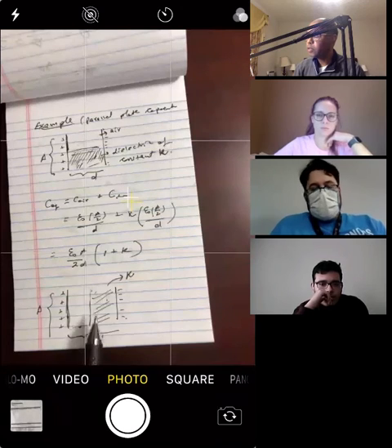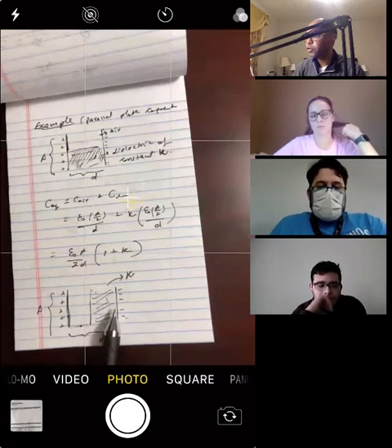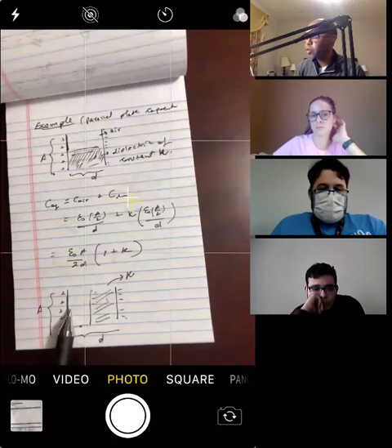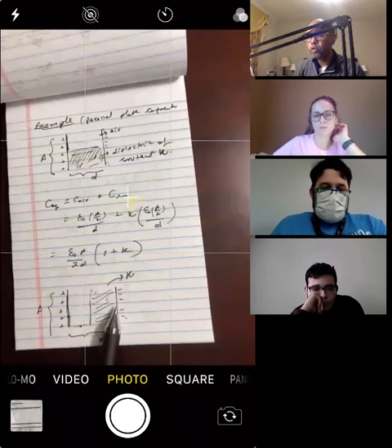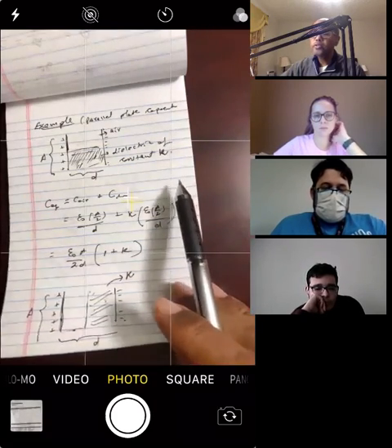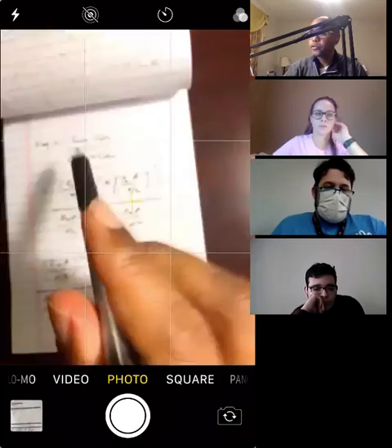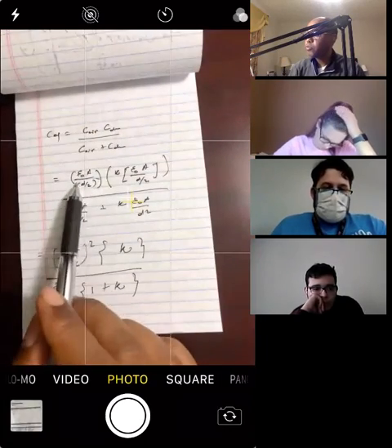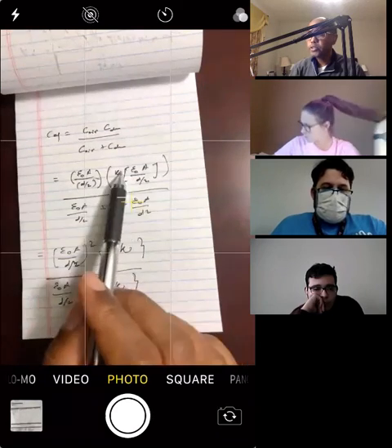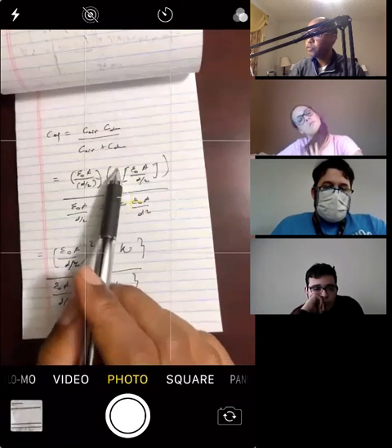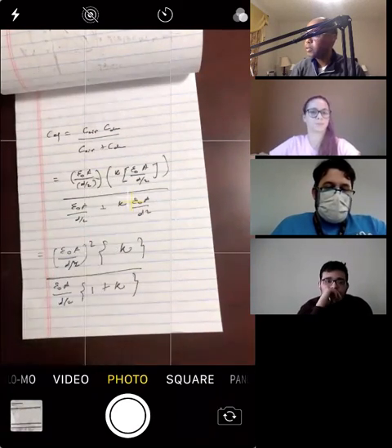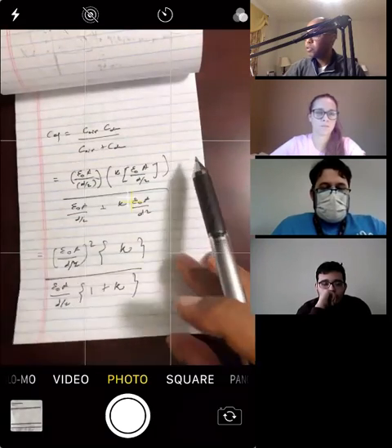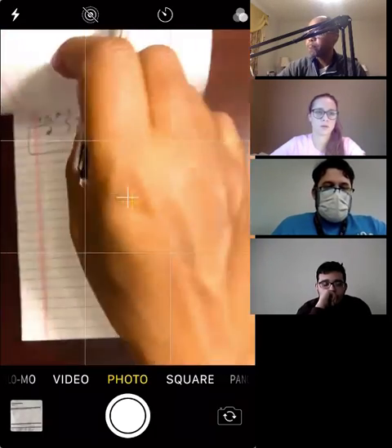Okay, so all I did is I put dielectric over here, and insulator over here. This one is air over here. So you can look at this as two capacitors, one with air and one with dielectric, and they're in series, so you've got to use product over sum to add them together. So this is the capacitance of the one with air, and this one the capacitance of the one with dielectric. The only difference is for the dielectric, you multiply by kappa. And then you add them over here, and I just factor out this, and eventually I got this expression over here.